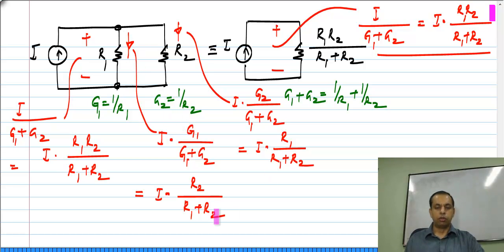Okay. Now, normally this is presented as ratios of resistors, in which case you have to take the other resistor, and if you have multiple resistors, you have to take the parallel combination of all the other resistors. So, for the current divider, the formula using the conductances is easier, but of course, you can use either of them. Okay. So, this is again another simple illustration.